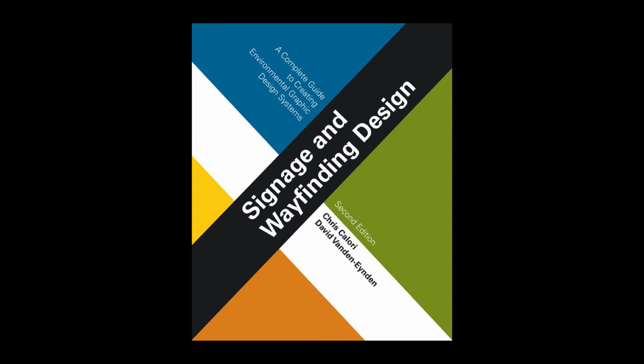However, in the case of a sign that's more complex in any form, say with tapering or multi-leveled panels, all sides may need to be shown: front, back, top, right side, and left side, possibly even along with some sections through it. The drawing number of a sign type's primary elevation, typically the front elevation, since it's usually the most distinctive, is entered into the message schedule for each sign number. See Chapter 6, the Hardware System, for an explanation of these drawing views.